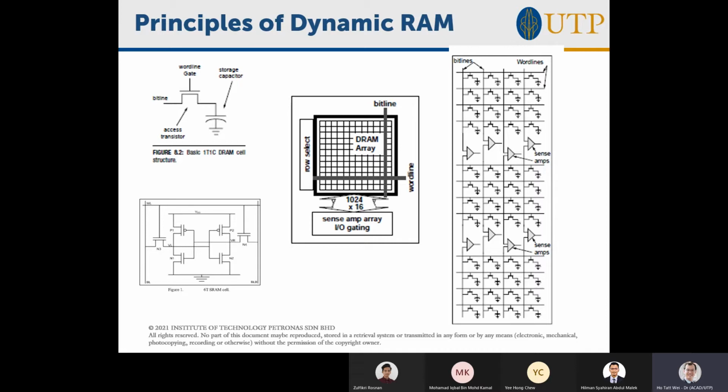You remove the charge from the capacitor, and then the data is gone. So after you read it out, there needs to be some kind of clever mechanism to restore the data back in. You can see you're paying all this trouble just because you're moving from 6 transistors to 1 transistor. You don't have these problems with the 6T. When you read out from a 6T, it's like digital logic. You just read it. The bit is always going to be set there unless you change it. But from a DRAM device, because it's a single capacitor, when you read it out, you destroy the bit. So you have to update it.